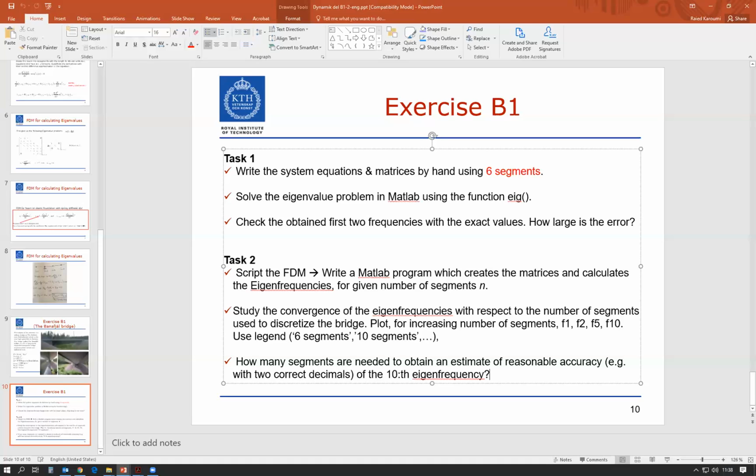At resonance, we will see that we will have to make a more complicated analysis. So both the Swedish design code as well as the Eurocode were updated about 20 years ago to consider the high-speed trains coming in Europe.